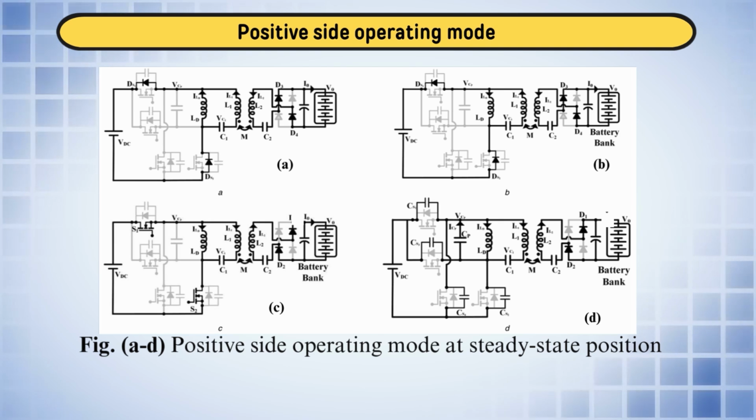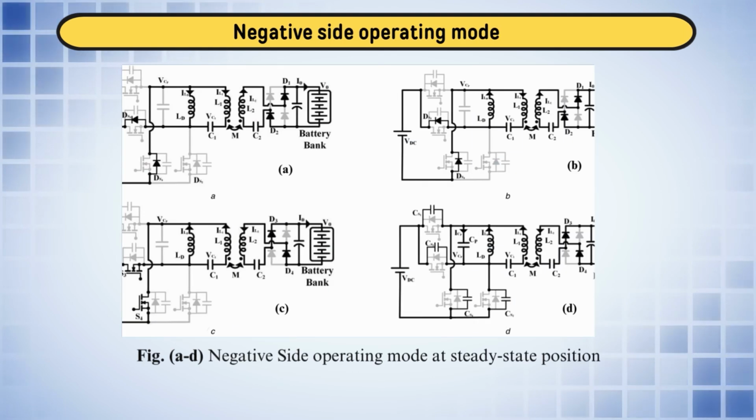Now, we have another unit. The conventional dual active bridge converter has some limitations. We have proposed a Scott connection based dual active bridge to increase the power density, as it has 2 transmission inductors, while a 3 phase DAB converter needs 3 inductors for power transfer. It provides a suitable interface between the medium DC link voltage and the low voltage battery.